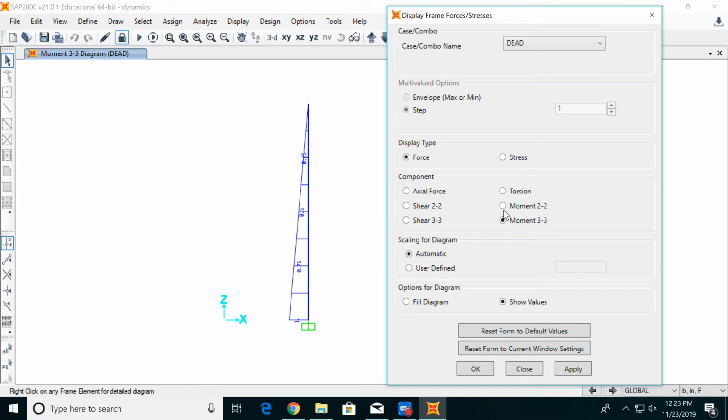In order to see other different component forces that we have, you can go under the component part of the dialog box, click on all 6 different ones, and see the values that we're getting. For this first shear, you can see that we have a negative shear of 0.1, which makes sense because we had a 0.1 pound force applied in the positive x direction. So that shear on the bottom ranging up to the top would be a negative 0.1 just to keep everything in equilibrium.